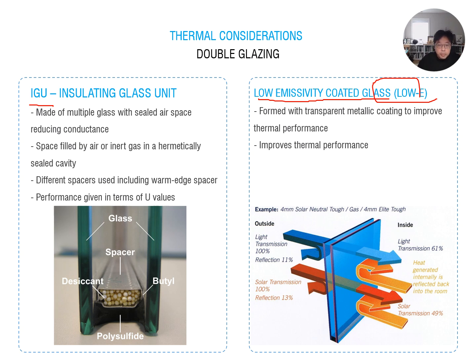The glass panels are separated by a spacer. This is a spacer. This is the most important technique when manufacturing the design of an IGU. The spacer system helps to create an effective thermal barrier at the edge of the IGU. So this one has a desiccant, which is to absorb humidity, making this space more vacuum and dry. Okay, so it means increasing the thermal value.